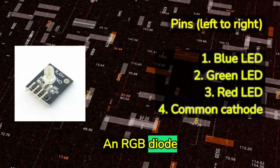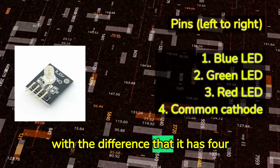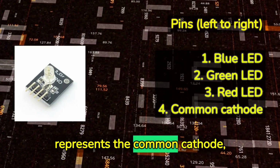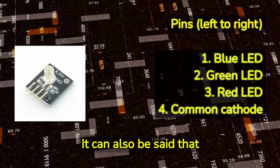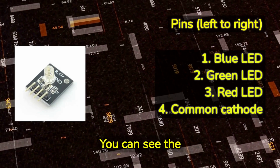An RGB diode is exactly the same as a classic LED, with the difference that it has 4 pins. One of these pins represents the common cathode, while the remaining 3 represent the anodes of the red, green, and blue LED. It can also be said that 3 LEDs are packed in one body. You can see the construction in the picture.